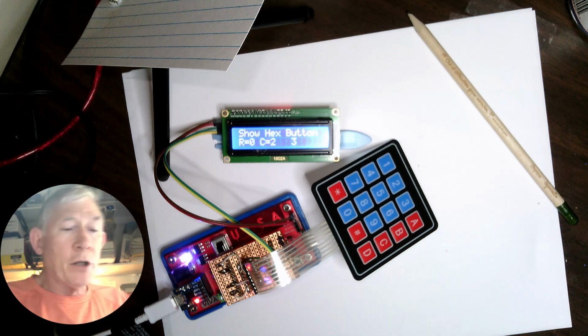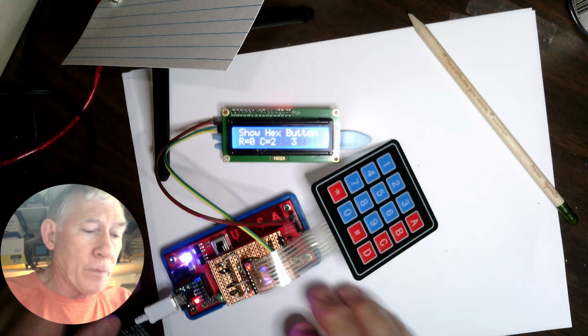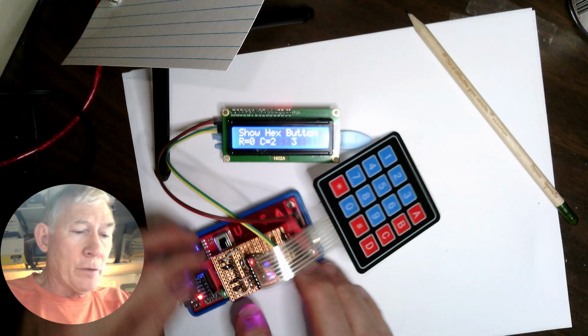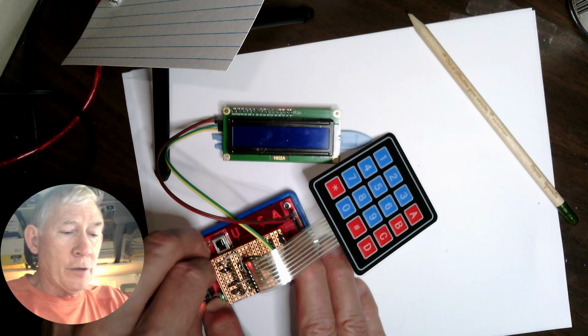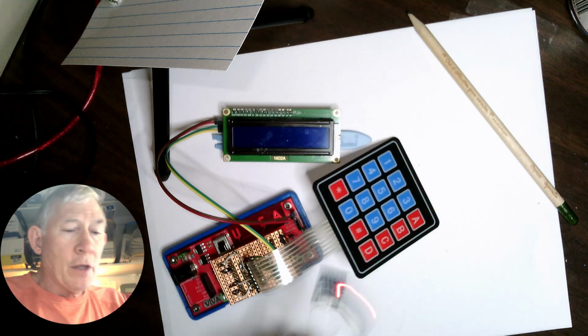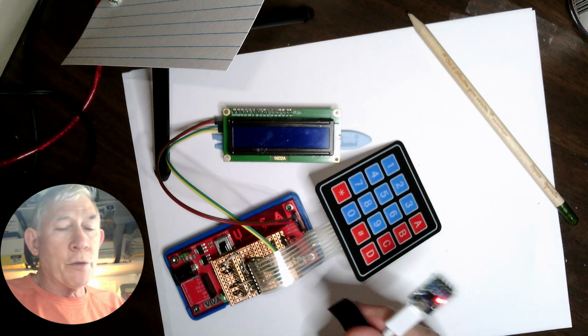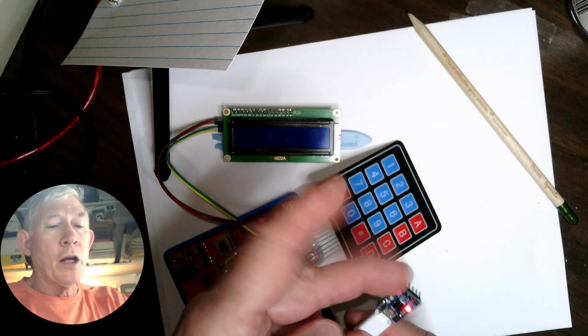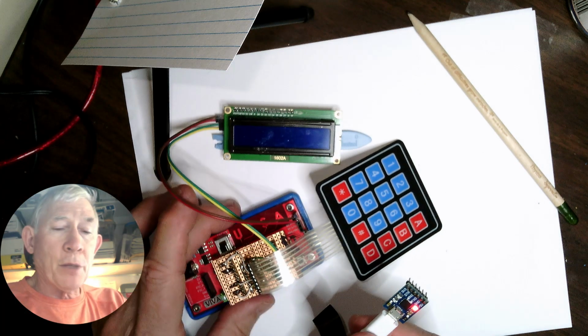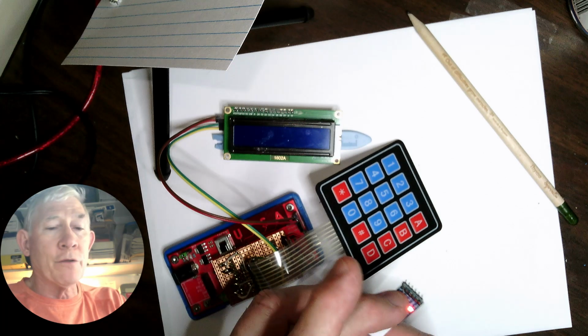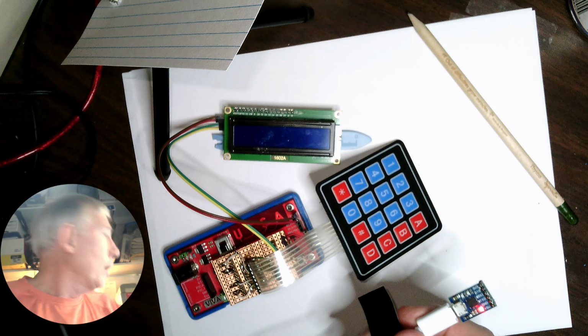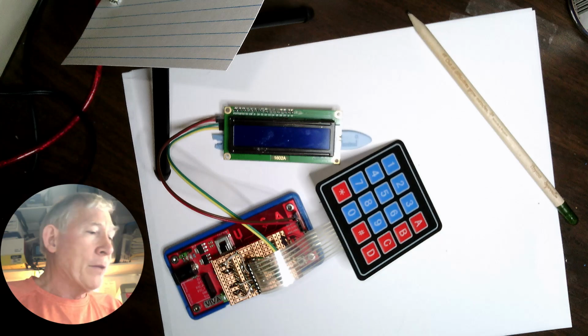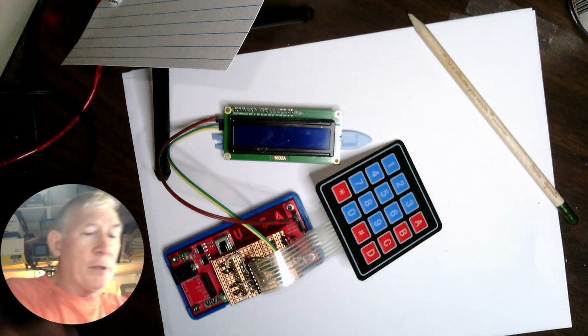Now let me take it apart. So the first thing, I'm going to turn off the power and disconnect this. So this is a CP2102. The Micro 1 students know that this allows us to send the UART signals from the PIC through a USB converter to a desktop, and they appear in a terminal window. And I did implement that.